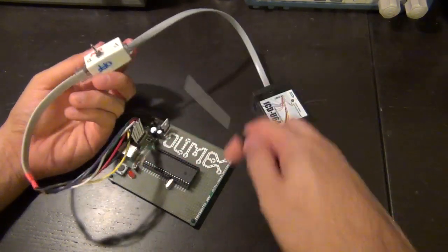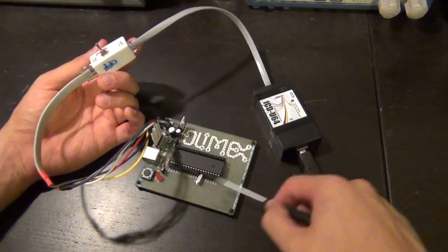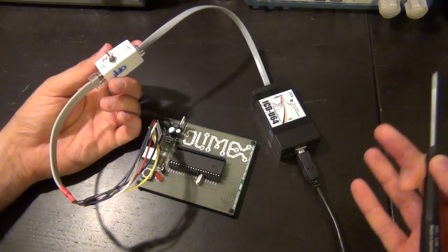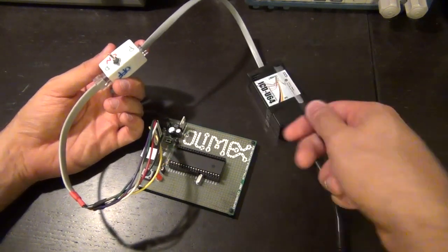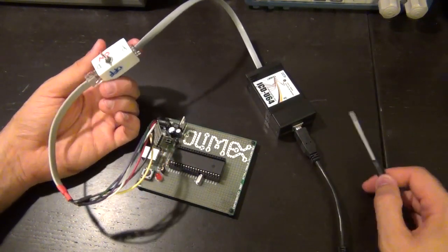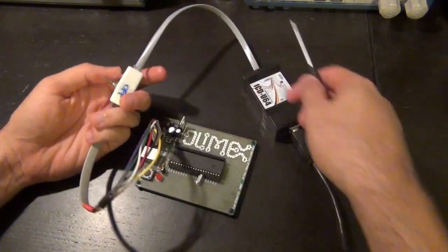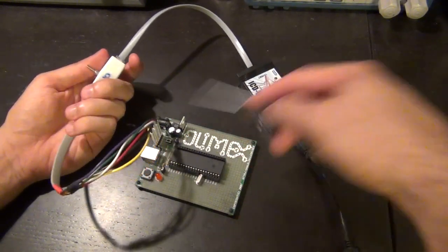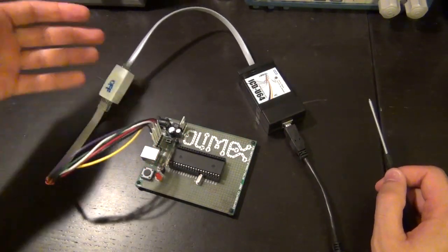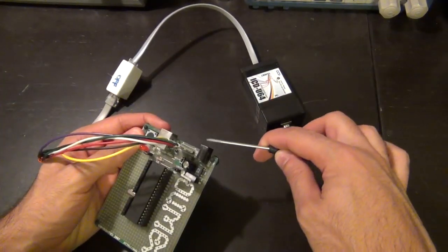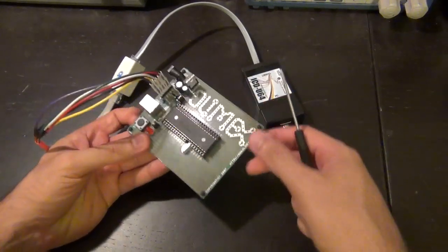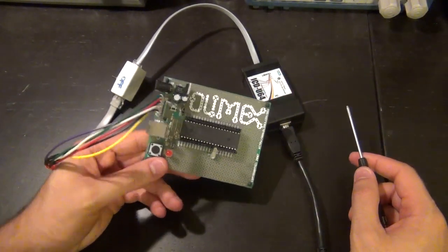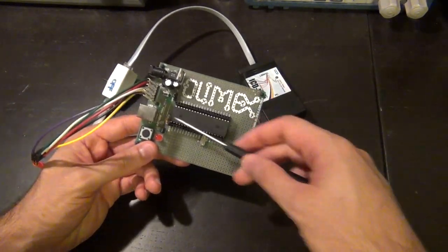The reason I have this is because sometimes your evaluation board could require much more current than this guy can provide, because the whole current comes from the USB port, so it's limited to 500 milliamps at most. So I can turn the current off, and that way it separates the VDD from this, and I can apply the VDD separately. If I want to apply the VDD separately, I just put in 12 volts through here, and the 12 volts goes through the voltage regulator, becomes 5 volts. This is a 7805 regulator, and then it powers this.